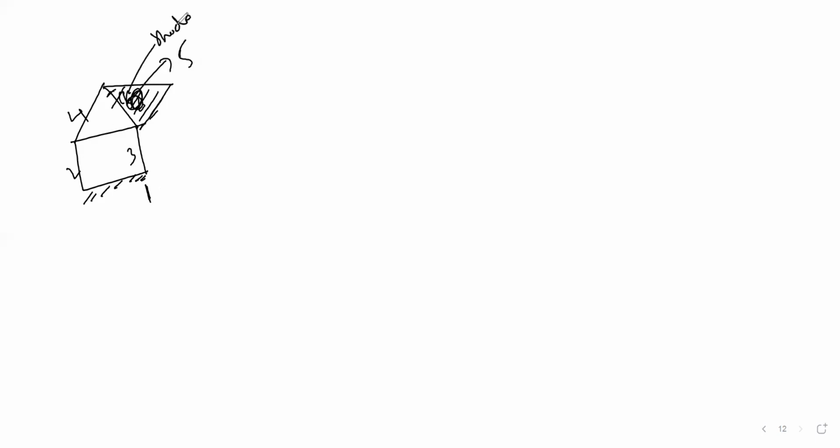Similarly, you can take it for lots of questions, like we have a question like that. And this is a shaded portion. Now you need to tell me what is the degree of freedom for this one. And this part is just fixed. It's fixed like that. So the fixed one, assume that it is one link. Now count it: 2, 3, 4. And this shaded portion, assume that it is one link, because it's totally fixed. It won't move. It's totally rigid. It's fixed, which means one link here.